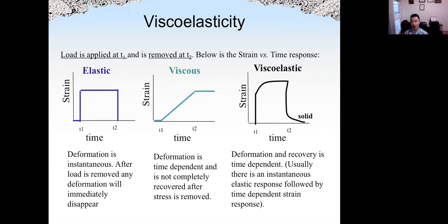For concrete, it has both an elastic component and a viscous component. At time t1, part of the strain is instantaneous, like here, and part of the strain is time dependent. It's slowly going up.